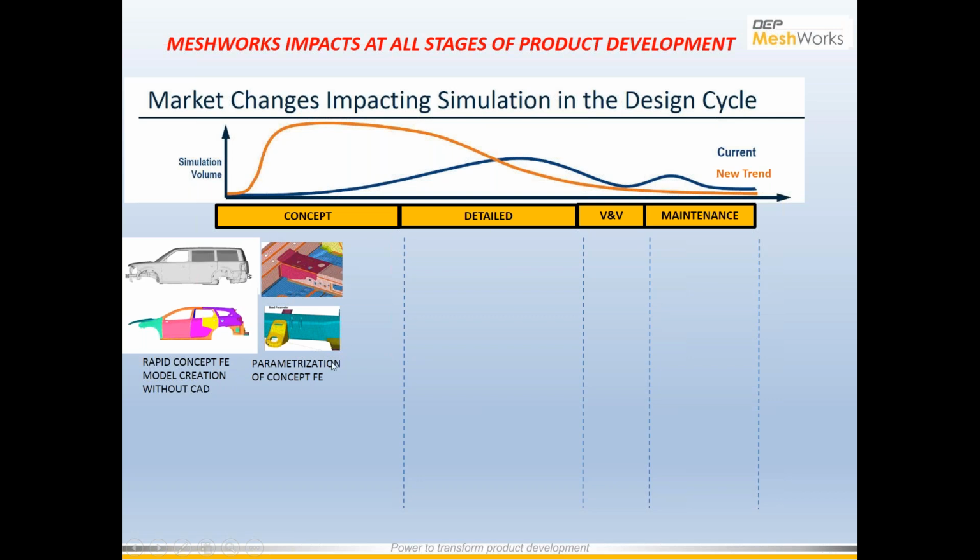Which means on the fly, you can modify the dimensions at the CAE model level itself. What you see up on the screen here, these are all animations of CAE models. And why should it be parametric? Because it allows you to subsequently run several iterations, like a design of experiments or an optimization and so on, so that you can achieve an optimized design even at a concept stage.